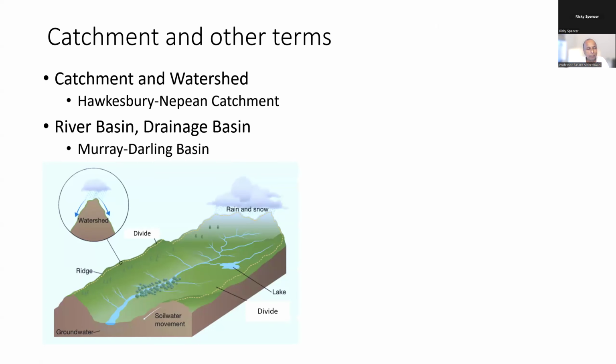When we talk about watershed, what we mean is that in the landscape there is always some ridge. When rain falls, water flows on either side of the ridge, and that marks the watershed area. So this is the ridge, and rain falling on this side flows through the landscape through different channels, creeks, and a river and into the ocean. Then comes the catchment. The catchment is the area which catches all the rainfall, and the watershed is the ridge where water flows in either direction as rain falls.